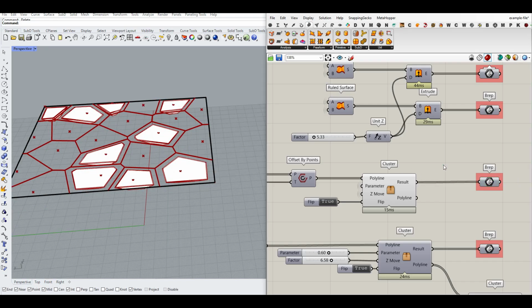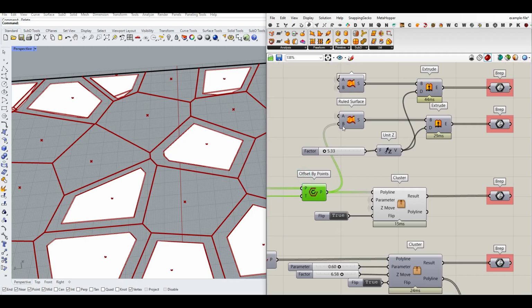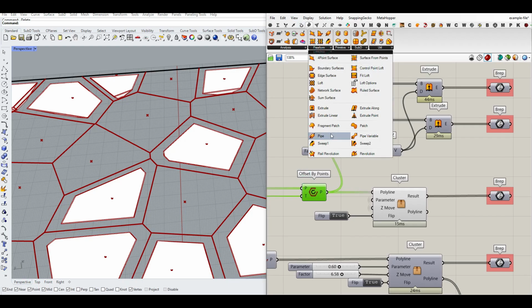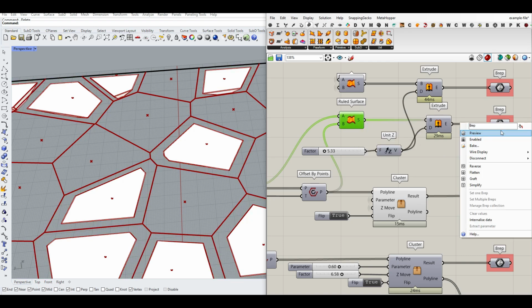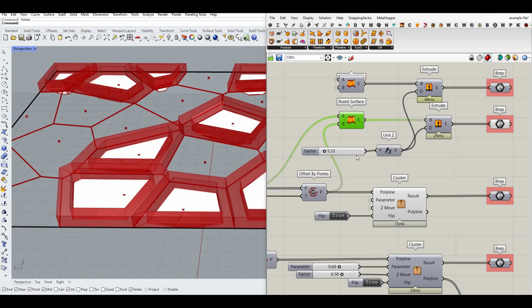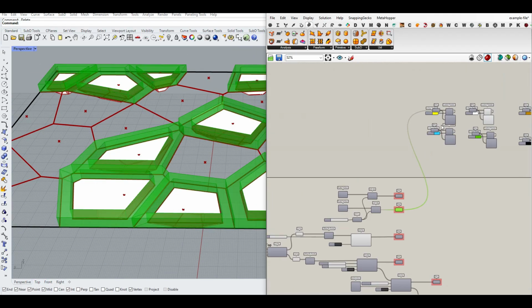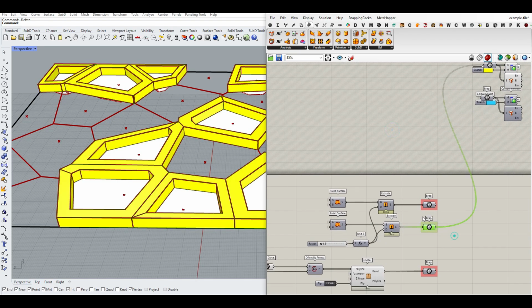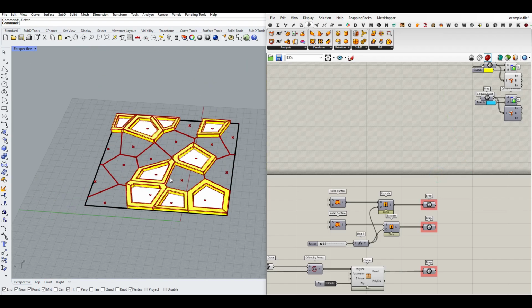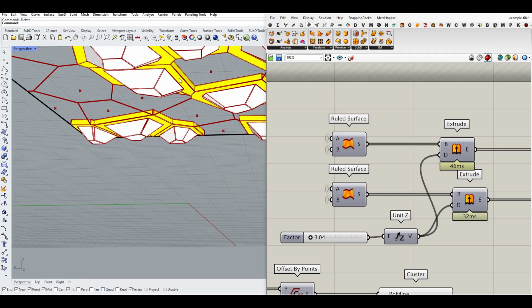Now that I have this, I'm going to also use these two polylines to connect them together. You can use the surface freeform ruled surface to connect them together, and a simple extrusion up will give you this one. You can control the extrusion of that. And because I've brought this up here, I'm going to turn on this preview, and we're good. We are good to go. We can have that as the parts of the cells that we want to give some border to that.